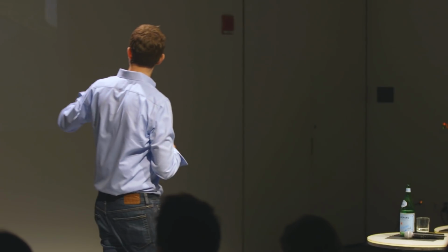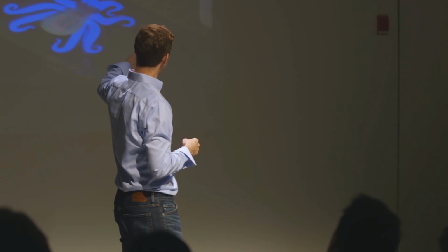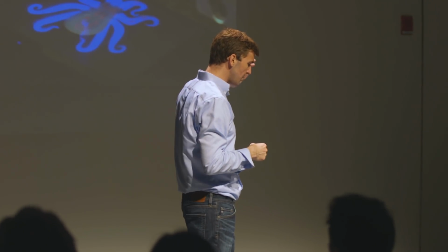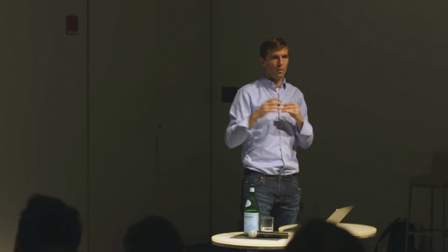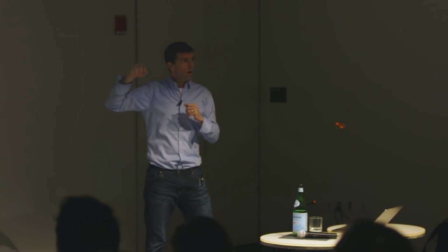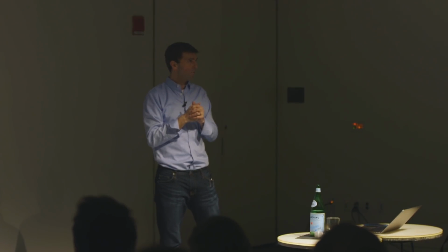So what happens is once this printing process is done, and so you're seeing the actuators and the limbs being printed now, once this printing process is done, this whole thing is cured, and so the elastomer solidifies. Then you still have this sacrificial ink within the vasculature. It turns out that the silicone-based elastomers that we use are porous to water, and the pluronic that's used as the ink for these things will break down basically into water and then self-evacuate. So you basically have voids that are formed more or less for free at the end of this process.